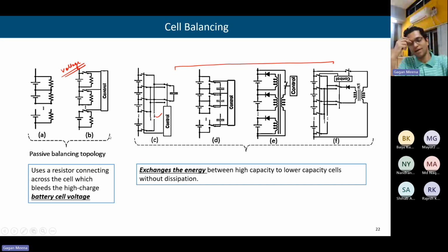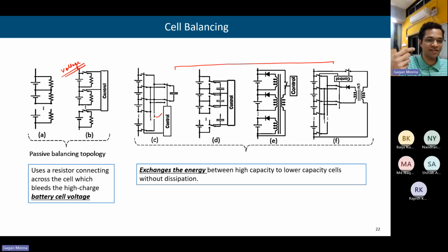We were having those regulators for fans, right? Those were resistive. Big boxes you would have seen. There were heating losses also across the resistor. But then we moved to power electronic based triacs for regulating the voltage, power electronic based regulators. They are very efficient, high switching devices. They switch at very high frequency, and the heating loss is also reduced.